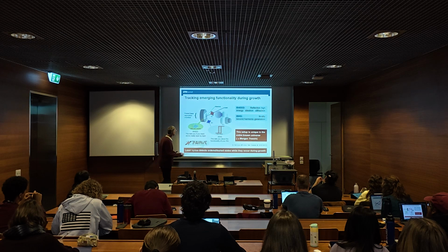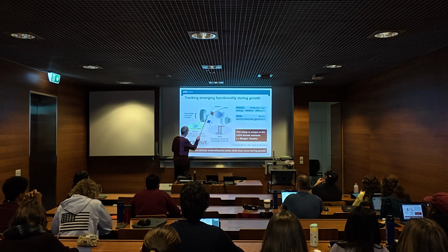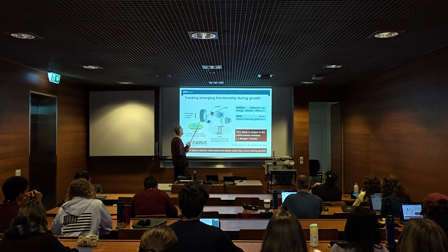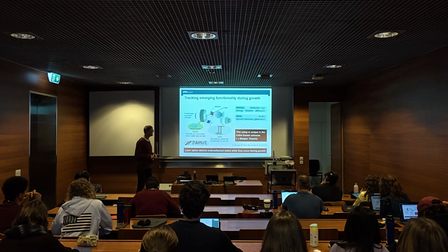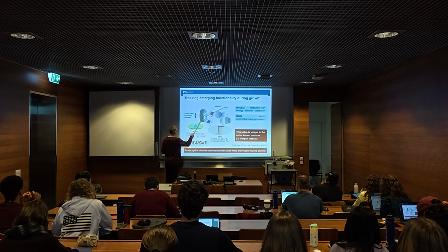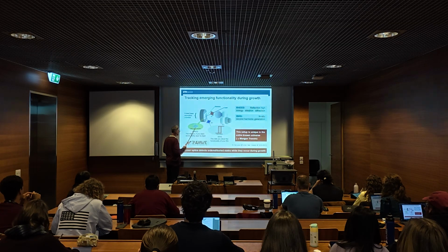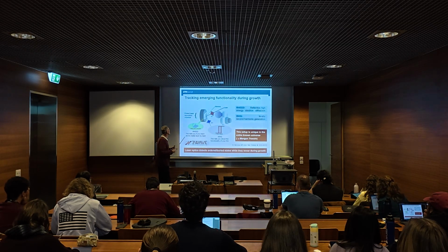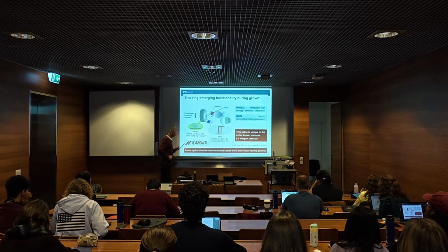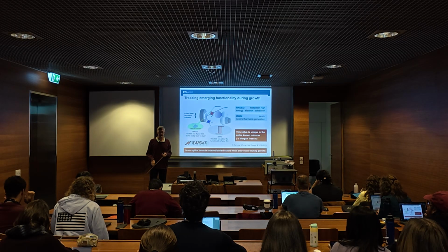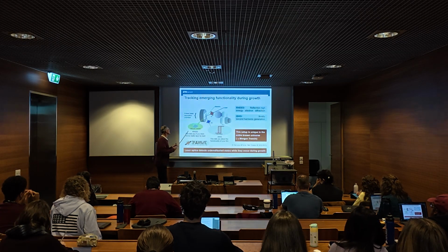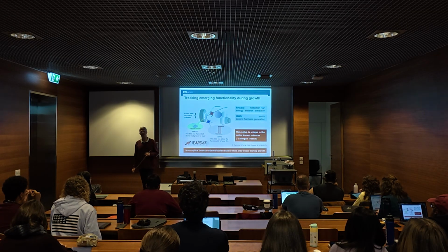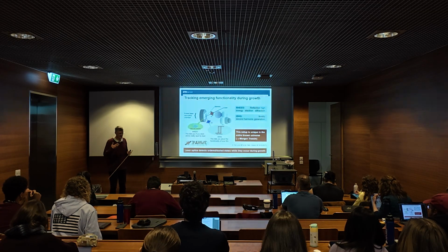Then you need the tool to tell you that you're growing a neat film. That is typically done with electrons. You have an electron gun. Electrons are reflected off this glowing thin film, and then you can see if it's a sharp reflex of your electrons, a diffraction reflex. Then you say, okay, it's nicely growing atomic layer by atomic layer. If that goes away, then you know something is wrong with your film. Okay, then you know that you have a nicely grown film, but you do not know if it does what you want it to do.